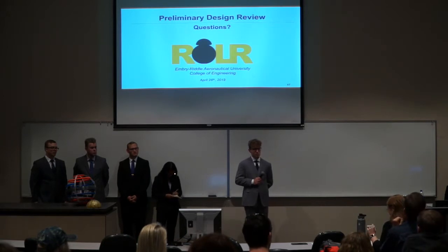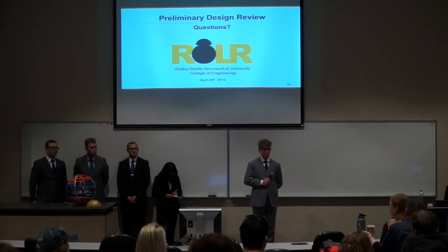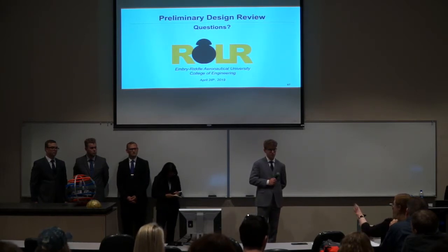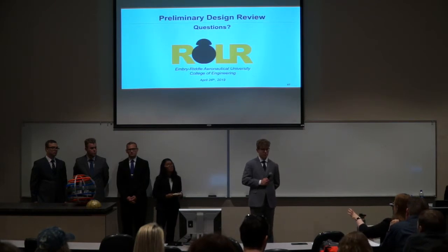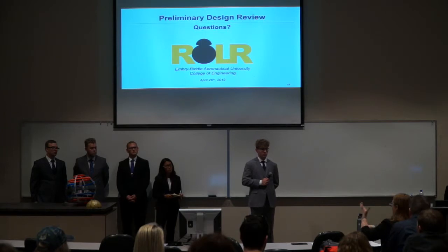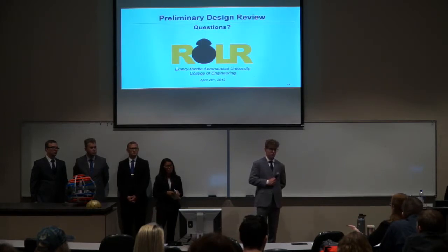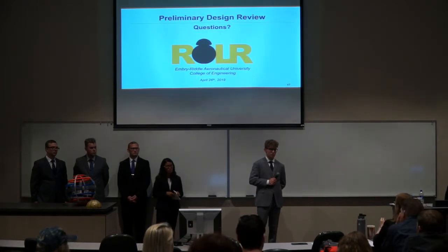Let's see here. There also wasn't very much about weight, CG location, volume. I think you've planned out what some of these things are, but you don't have requirements on them. So it seems very haphazard, like you're flying by the seat of your pants designing this thing, hoping that it'll work, and not working to what your sponsor is saying that he can provide.